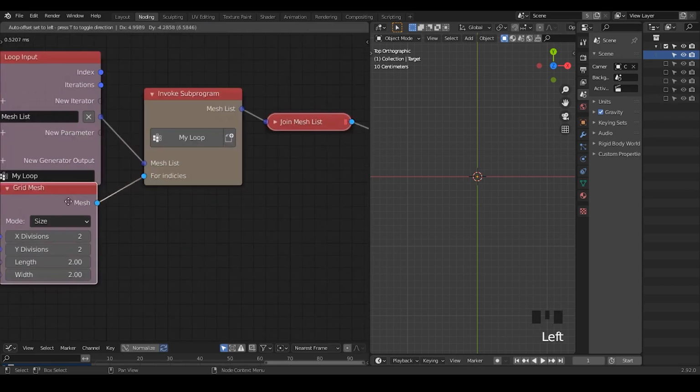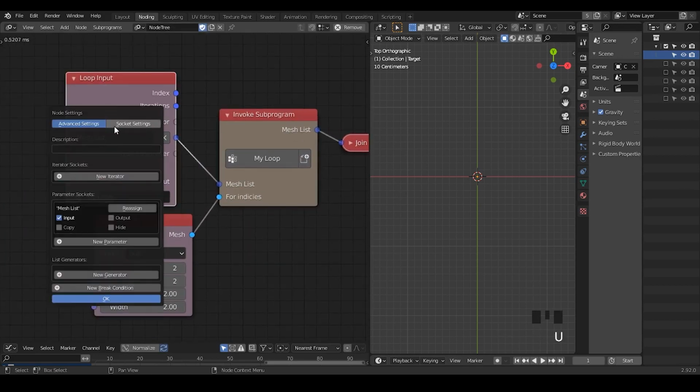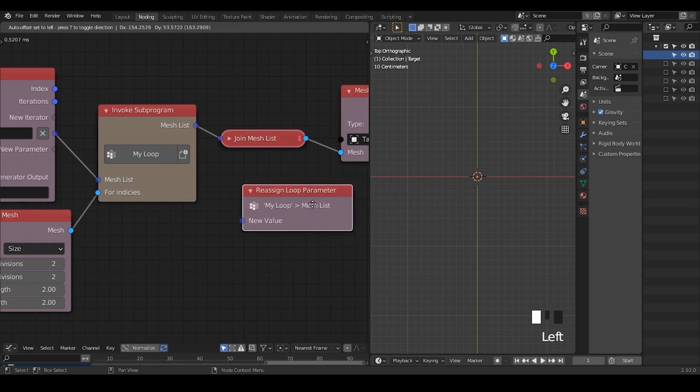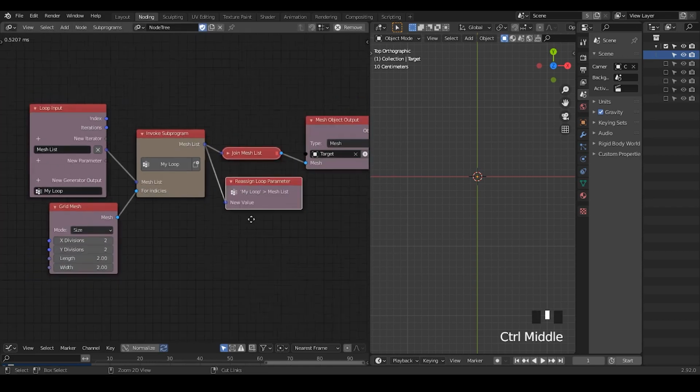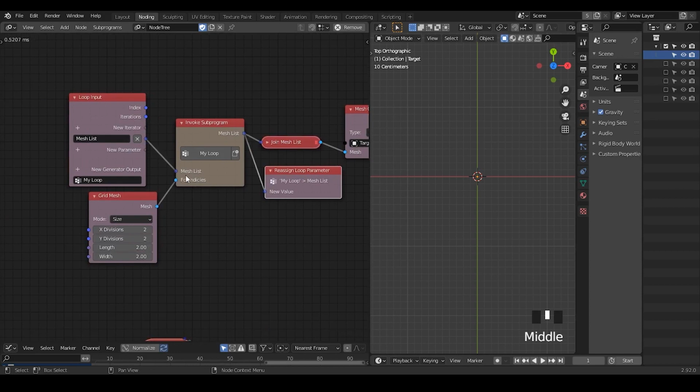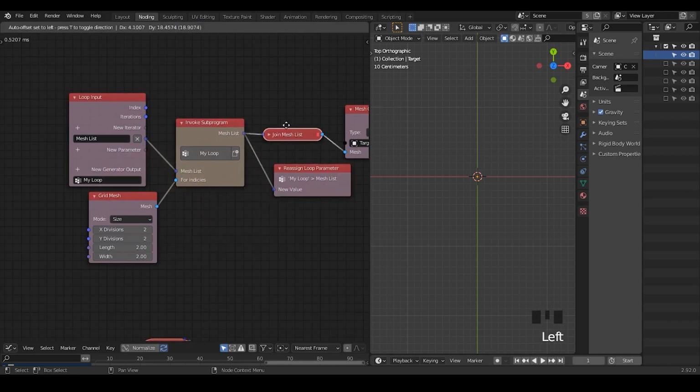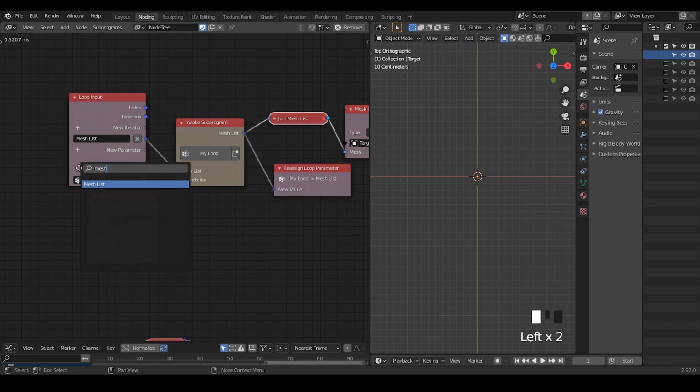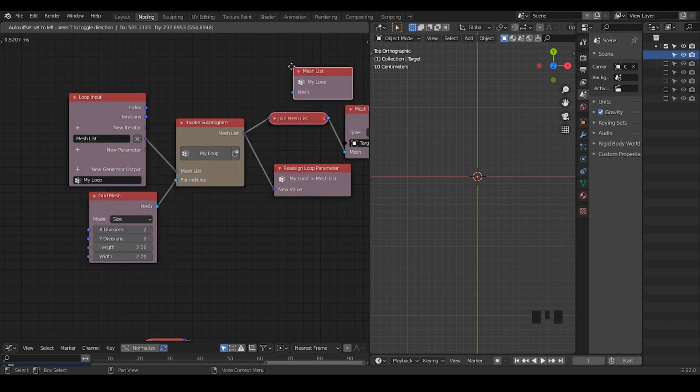What we do here has actually been explained in my advanced loop video, the advanced parameter or whatever in the loop. I don't know how to explain it. So what we do is take the reassign. Actually, you just need to reassign. Once you take this reassign, what happens is you put a mesh list into the place, and after it outputs everything, you input everything back to the same place. Then this is perfect. We're going to output the mesh lists all together.